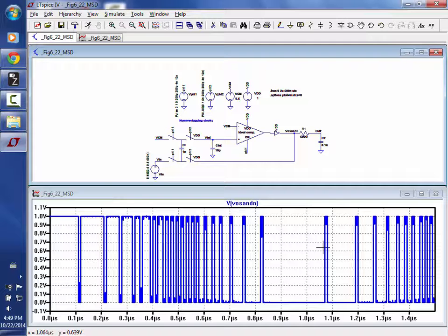So the point is, I think there's something to be done here in low power A to D converters, but what's the big thing I'm not showing in here that draws power? You should know, Angshaman. I'll give you a hint. Phi1 and Phi2. Yeah, you need a non-overlapping clock generator. You can get your NAND gates and inverters, but they'll draw probably as much power as all of this. So when you do the simulation, you have to generate your clocks as well.